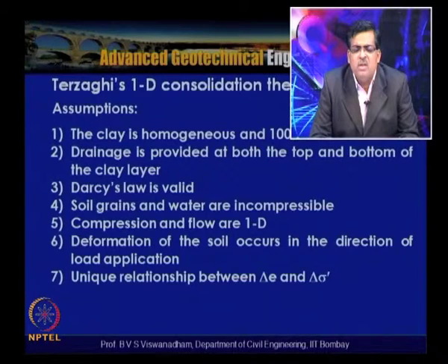That means that here in this case one dimensional is assumed, but in the latter part of these lectures we will also be discussing the three dimensional, as well as the two dimensional flow. If that happens, there is a possibility that the consolidation can be accelerated, and the deformation of the soil occurs in the direction of the load application.